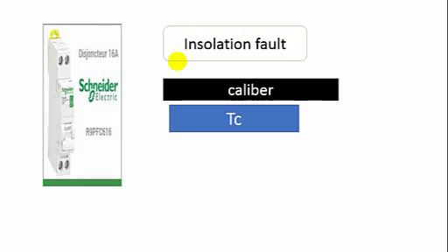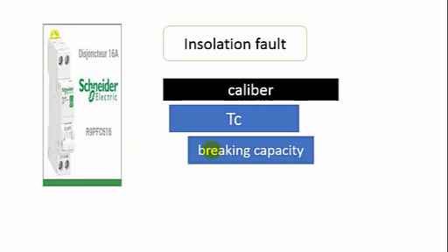We concretize the maximum disconnection times, by which we can determine the tripping times Tc, and we concretize the breaking capacity.